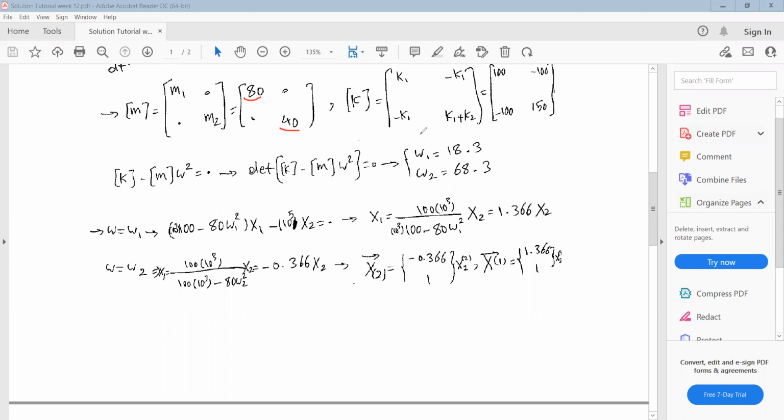And then by calculating the determinant of the matrix of coefficients, we can extract the characteristic equation, and the roots of this equation will be the frequencies of the system. The first frequency, which is the fundamental natural frequency, and the second frequency of the system.